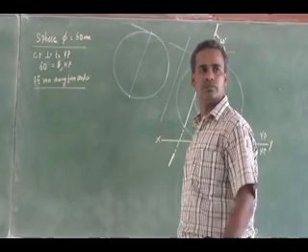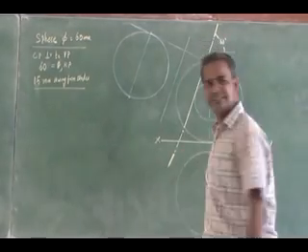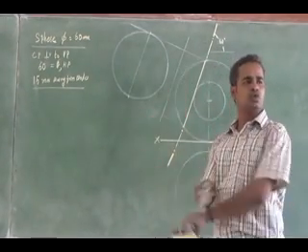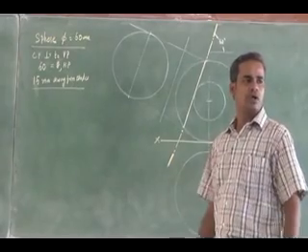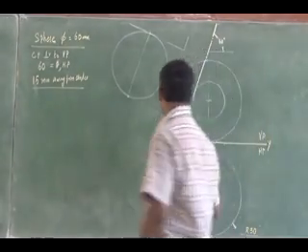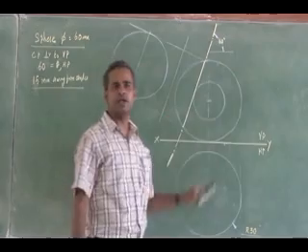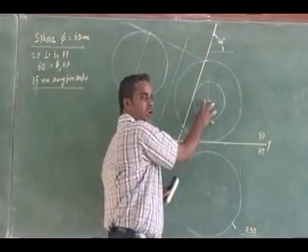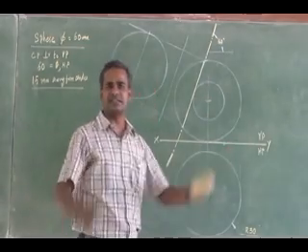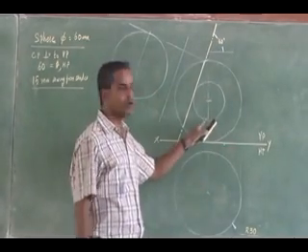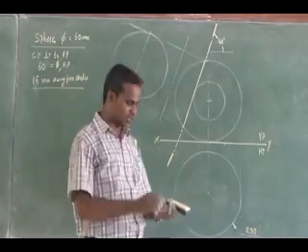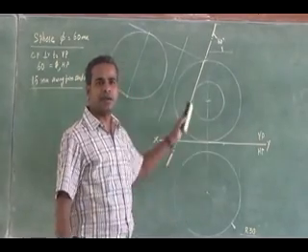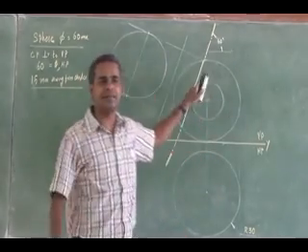Right. So stop. Draw the sectional top view and true shape of section. See here, draw the front view and top view of the sphere. Both are circles. The front view will be touching the reference line since it is kept on the ground. So the front view and the top view are both circles. And I have represented the cutting plane here.